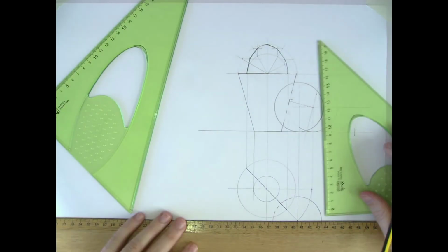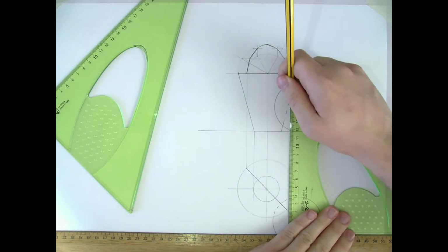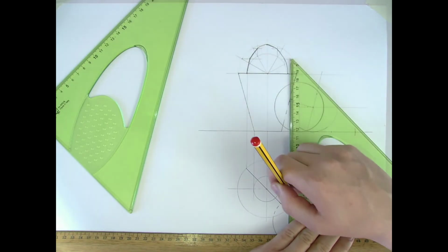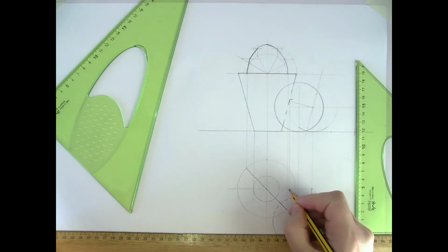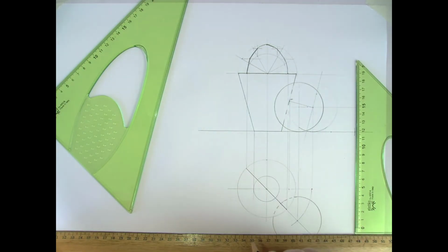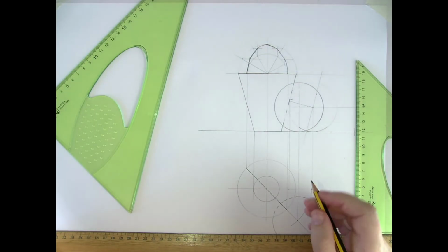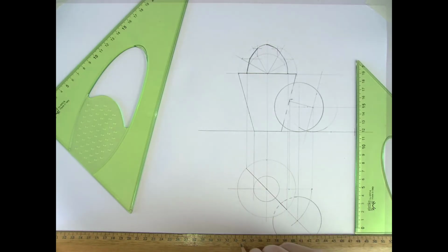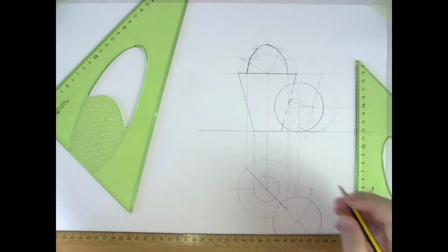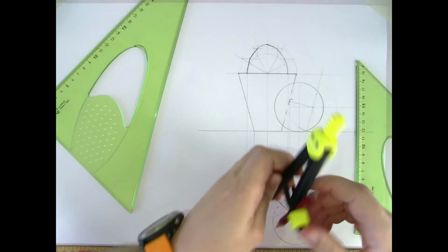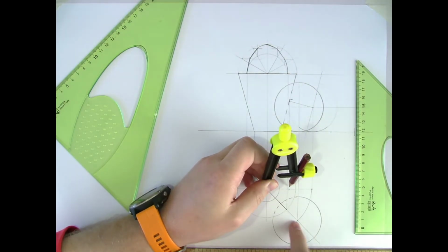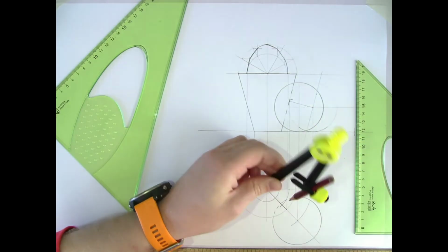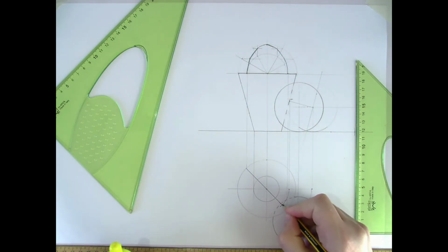Locating that same point now down in plan, it's going to be on this line joining center to center. So the point of contact is always going to be on a line joining the axis of a cone to the center of a sphere, because it's the shortest distance between them. So that's this point. So we're going to rotate that now around onto the correct line joining from the axis to the center. This one. This is the point of contact that I'm looking for.